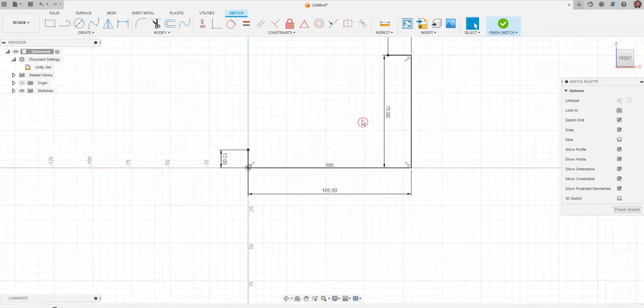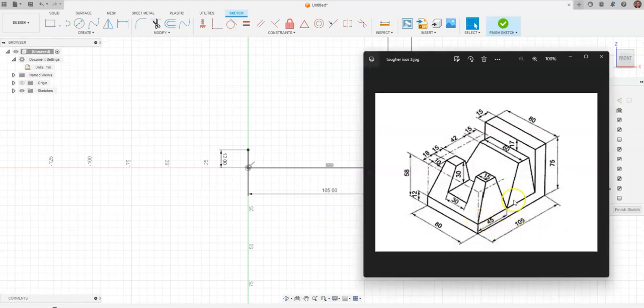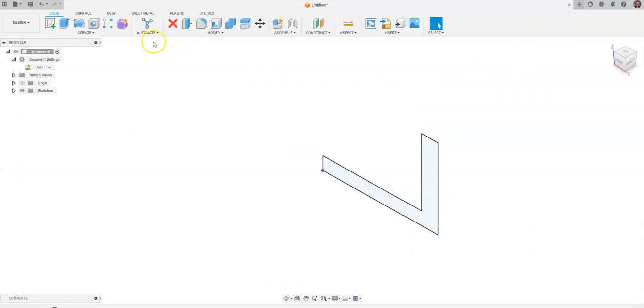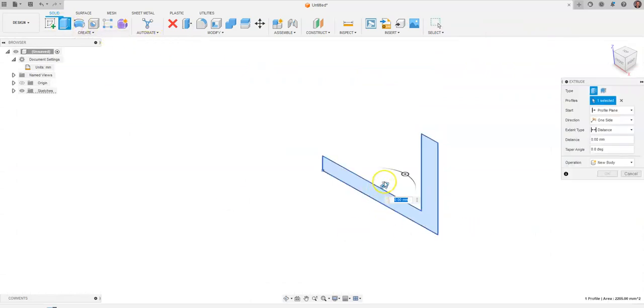Now what you'll notice is it didn't really give us the distance dimensions of this in here. We could infer some of it, but we're not going to do that. What we'll do is we'll grab a hold of the line, and I'm going to click on our point over here, and I'm not going to click yet. I'm just going to drag up and reference this point up here, and as I drag straight down, you're going to see that dotted blue line. I now have a line that snaps right underneath that line because I can see that dotted blue line. I'm going to click. I'm going to come straight up, perfectly snap that into place. I see the light blue color in our shape here because that tells us that Fusion sees a profile that it can create a solid from, such as the extrusion we will do next.